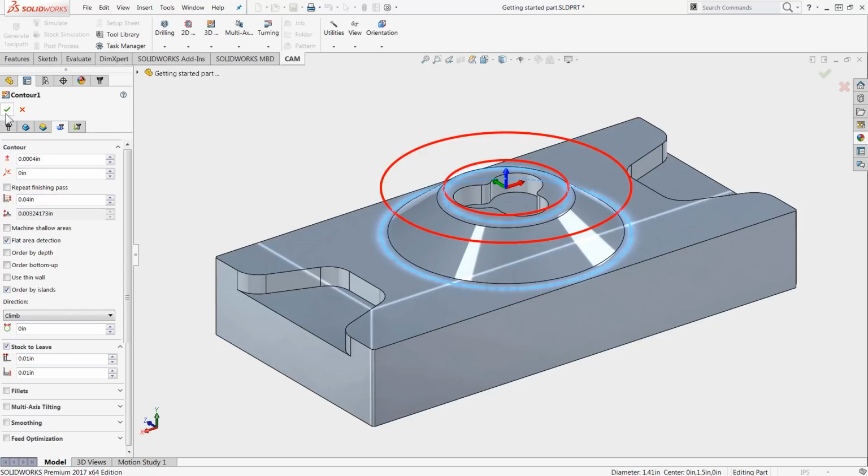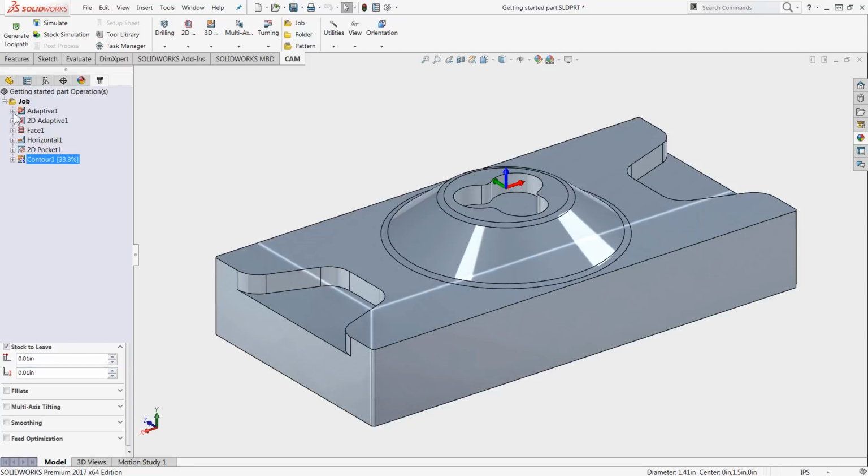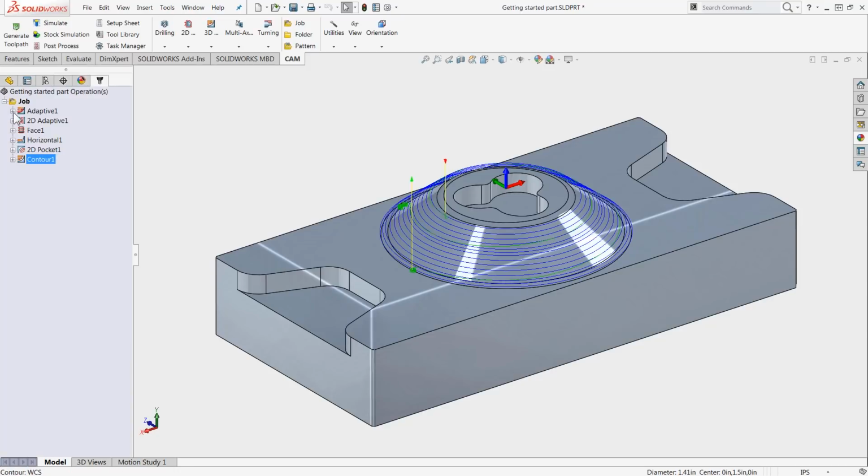When it comes to deciding on a finishing 3-axis toolpath, there are always two factors: required surface finish and time. Time equals money, right? The smaller the step over, the better the surface. But also, with a smaller step over come longer cycle times. Let's get our feeds and speeds straightened out so we can make a good judgment on the last surface machining.